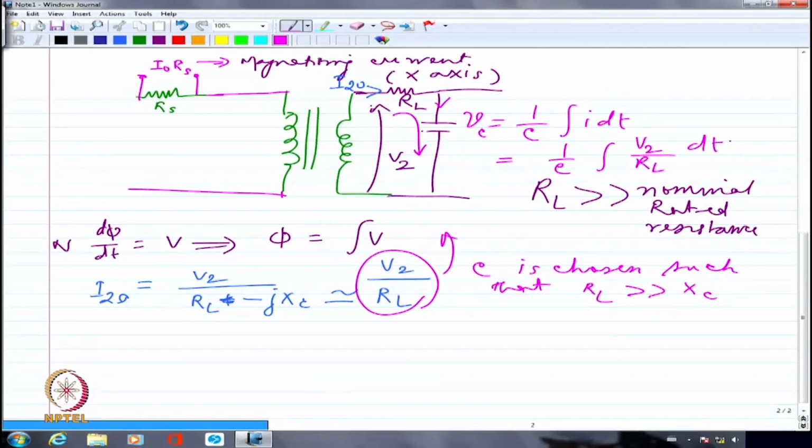So we are integrating the voltage indirectly by passing the current through a capacitor. So what I am getting as the capacitor voltage, which I am plotting on the y-axis of the CRO, is a measure of flux. Of course, it has some multiplication factor like 1 by RC or whatever. I do have definitely a multiplication factor, no doubt.